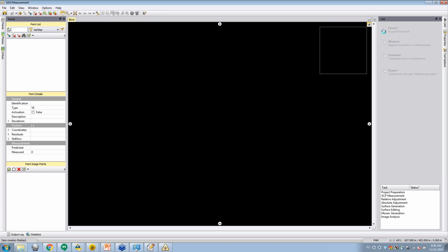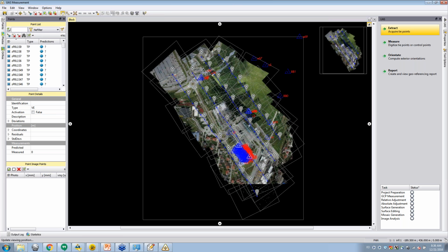Now that we're still waiting on this, I'll actually walk you through the setup of UASMaster and the georeferencing page here. So this is where you perform your relative measured ground control point and then your absolute adjustment with a camera calibration. These steps are pretty much sequential. You have different strategies, depending on data, to improve your processing speed. You can select some ground control points, and this will actually speed up your tie point extraction because it gives the software better initial estimates for its optimization problem. But our first step would be to extract tie points.